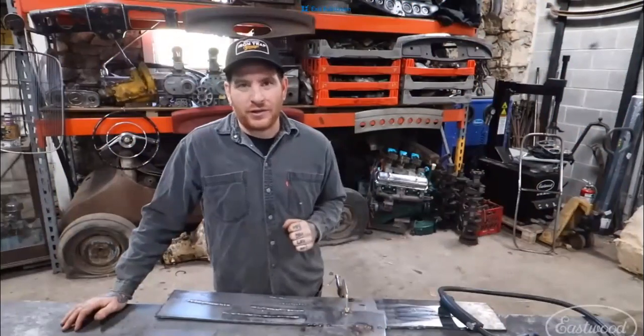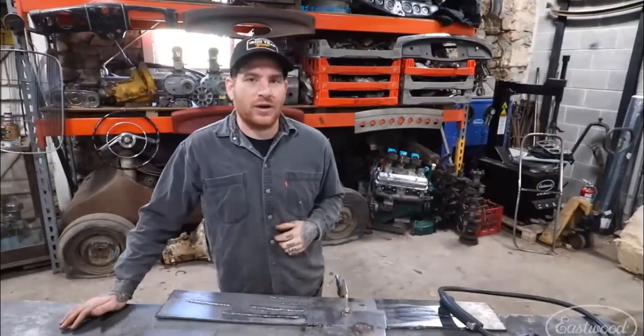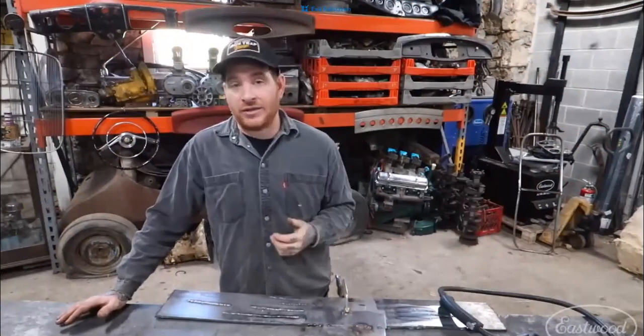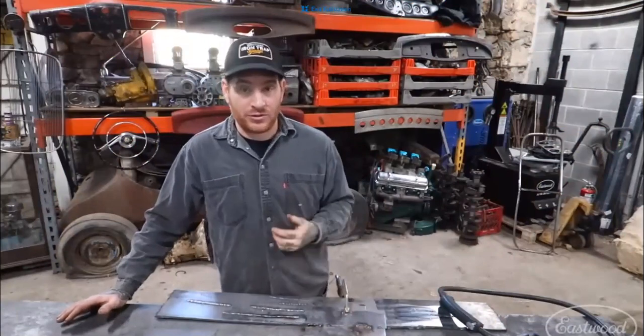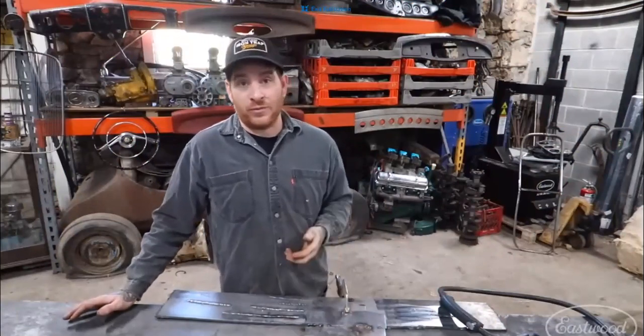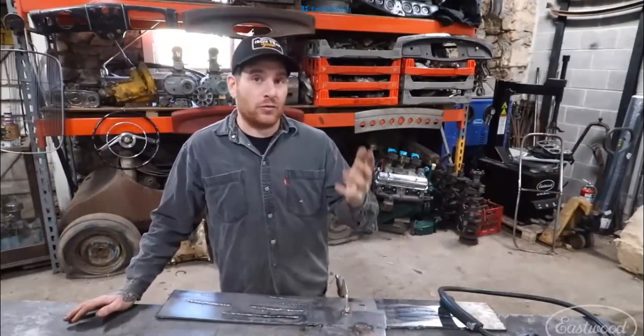The fifth and final reason on why your MIG welds might suck, or you're having a problem with your MIG welder, could be something that you wouldn't have guessed. That is the input going into your welder. The power supply or power source that is coming into your welder could cause a problem and make your MIG welds suck. So you need to make sure that you have a proper breaker for your welder.